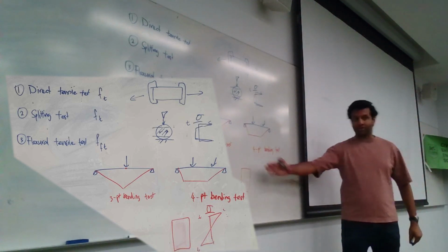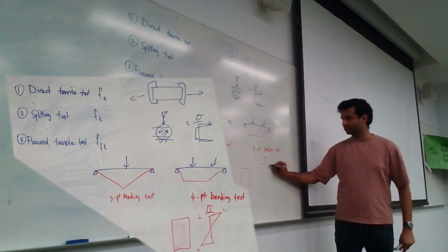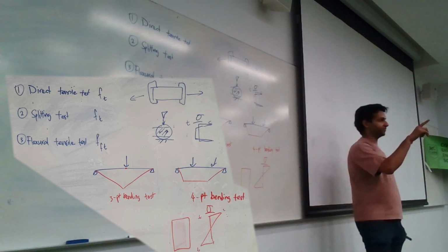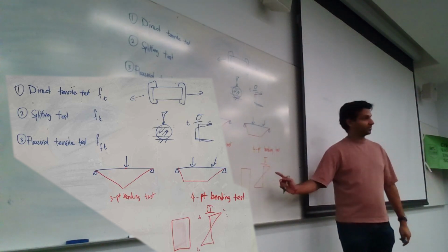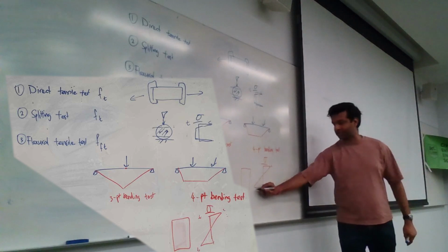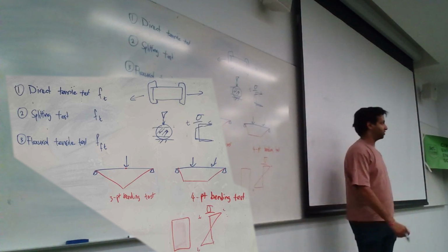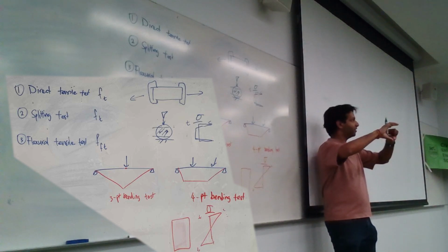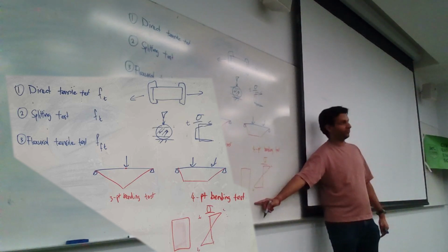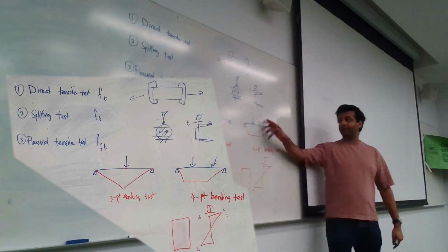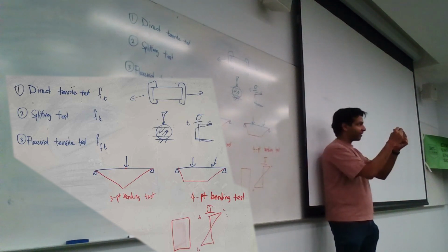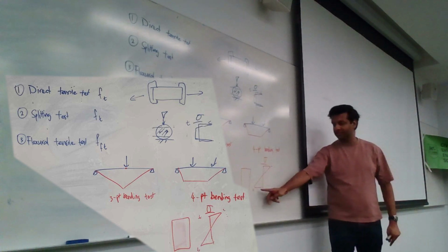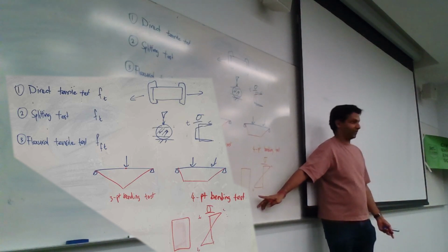The stress distribution along the cross section, if you recall from Eng 2400 and the mechanics of materials, we did this, right? Compression on the top, tension on the bottom, this is the distribution. So if you know the total moment that you're applying on that part, you can easily solve what the tensile strength is. And if you apply the loads until something cracks at the bottom, the point at which it cracks is the maximum tensile strength of concrete, okay?